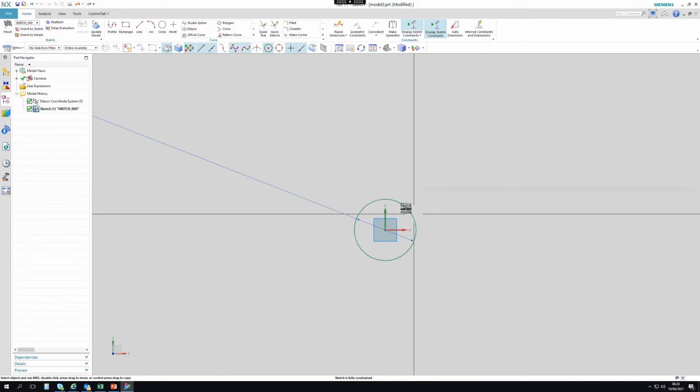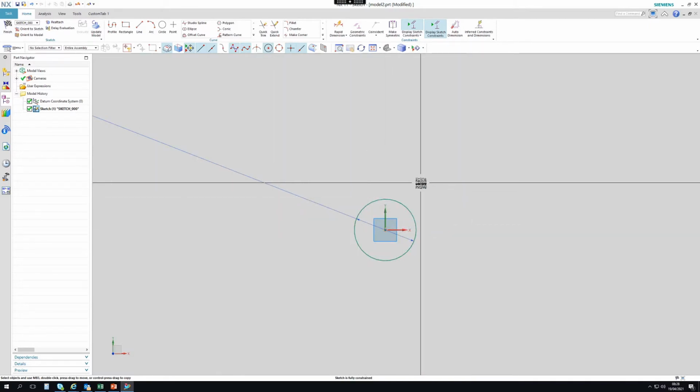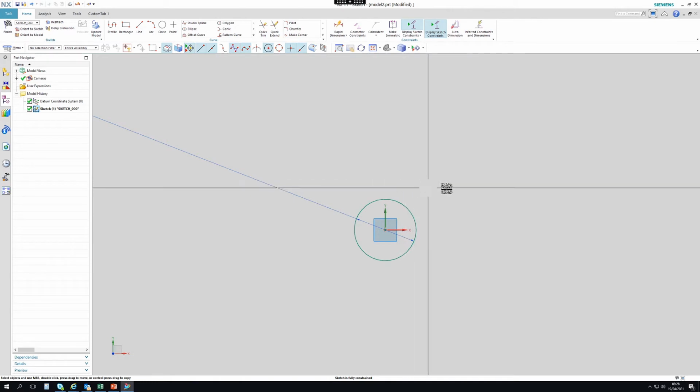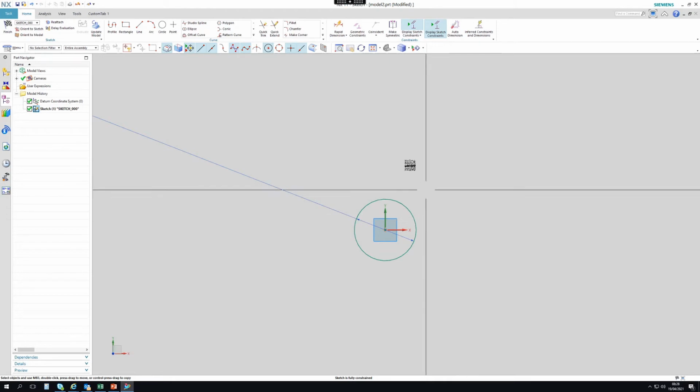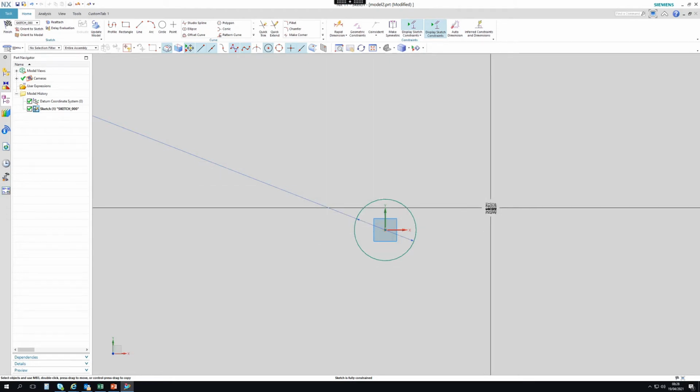So that's my positional tolerance circle. The way positional tolerance works, because we've got theoretically exact dimensions, if the positional tolerance works on one hole, it works on all the holes. So we only need to work it out on one hole.